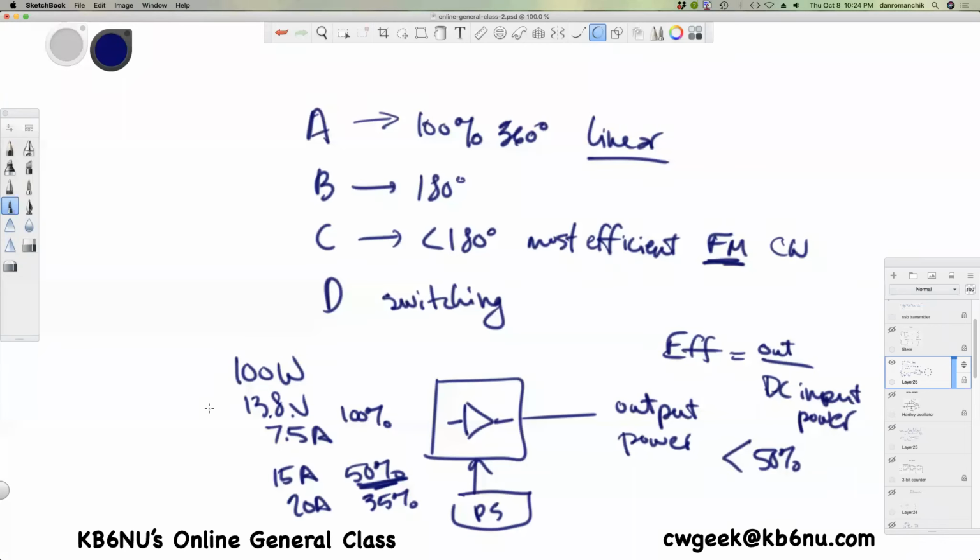And then there's finally a question here about linear amplifiers. A lot of times linear amplifiers use tubes. They actually still use vacuum tubes. And they can become prone to self-oscillation. The reason for that is, when we talked about the stray capacitance between the grids, the plate and the grid. Well, that can happen. So what you need to do is prevent that from happening, you need to what's called neutralize the final amplifier stage.